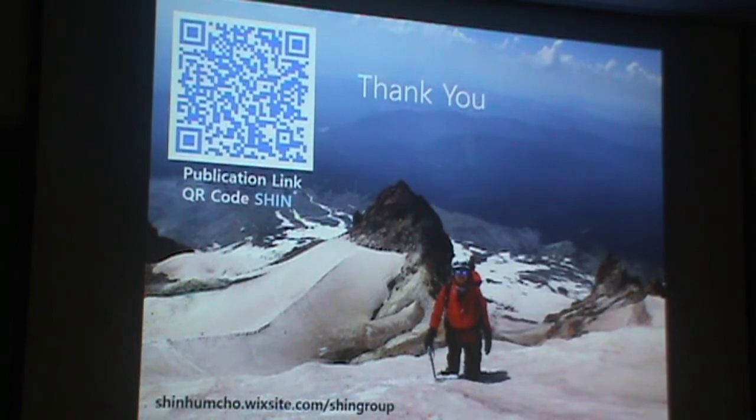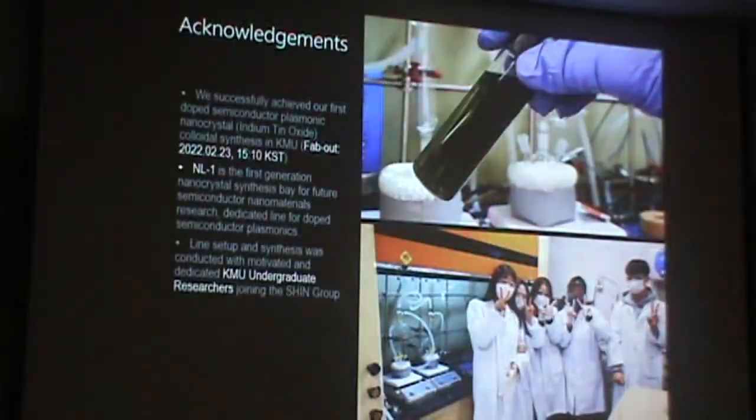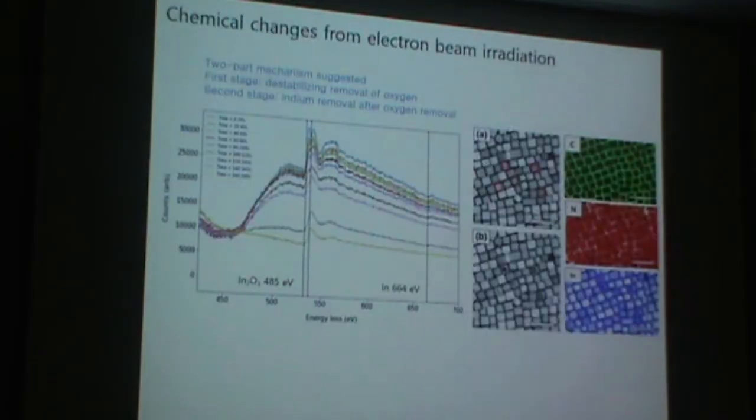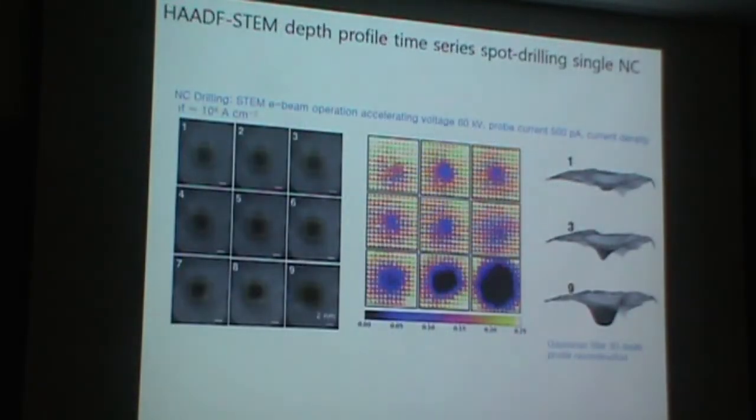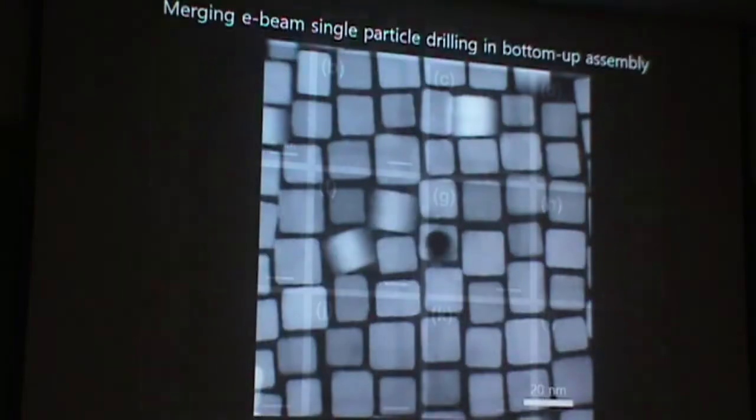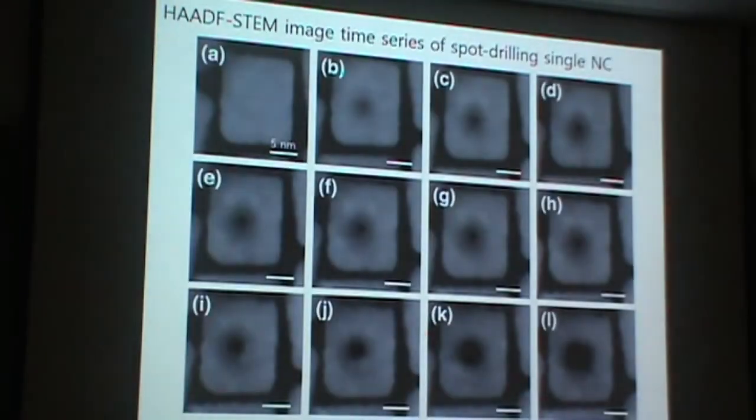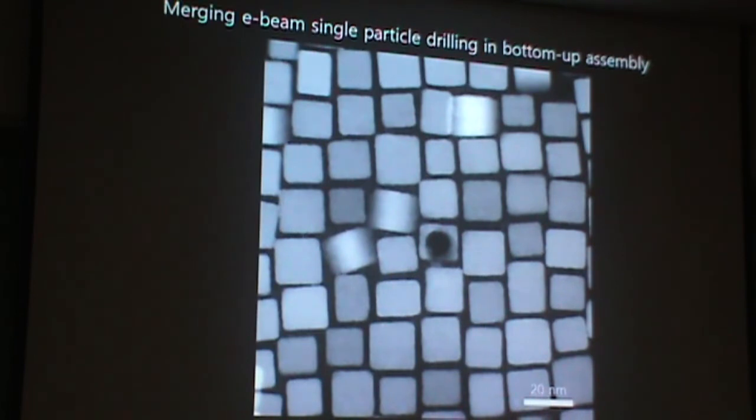With electron beam lithography, you start with the cubes and then you make a hole in it. But once you shoot the electron beam on it, the atoms that are discarded, are they just lost, or are they redeposited? It does break the vacuum a little bit, so this is where the electron microscopist doesn't really like it. In this case, it does seem to deposit. If you look at the inner particle gap, most of it is lost into the vacuum trap.